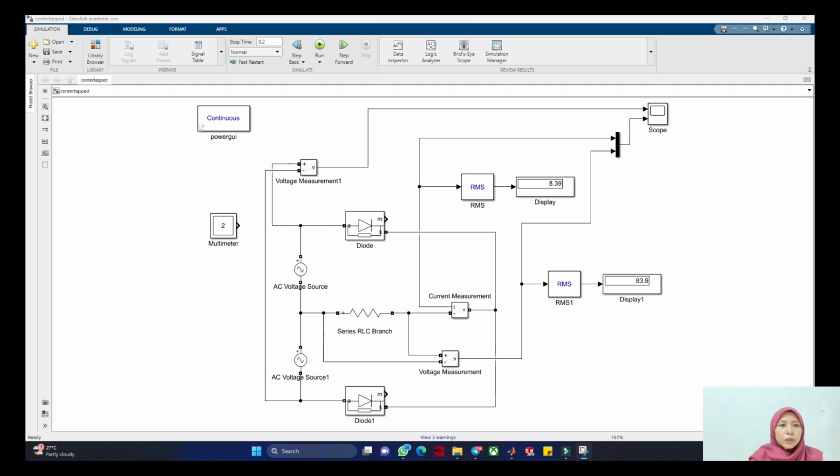A small voltage is wasted at the diodes D1 and D2 to make them conduct, however, this voltage is very small compared to the voltage appearing at the output. So this voltage is neglected. The diodes D1 and D2 are commonly connected to the load RL, so the load current is the sum of the individual diode currents. We know that a diode allows electric current in only one direction. From the above, we can see that both diodes D1 and D2 are allowing current in the same direction.